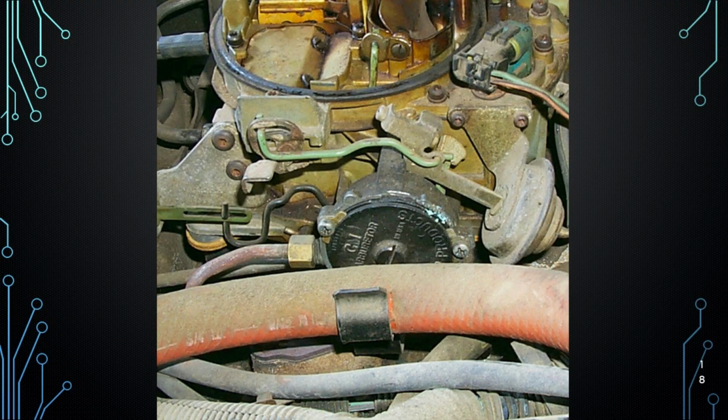The black connector on top of the carburetor with two wires is most likely for the bowl vent solenoid. In electronic feedback carburetors, this solenoid controlled the venting of the float bowl. When the engine was off, it could close the vent to prevent vapor escape. When running, it would open to allow normal bowl venting. It was part of the evaporative emission strategy of that era.